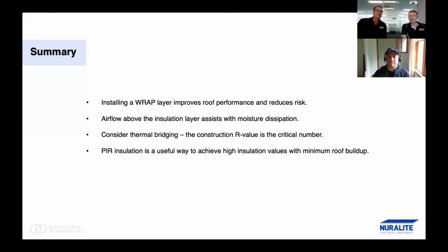Generally, what I find is that if there is a door threshold connected to it, then you need a floating deck. Yep. And I guess that's part of Nuralite's offering as well. We have a full Codemark certified trafficable walking deck warm roof solution if you need one in conjunction with our Nurajacks.